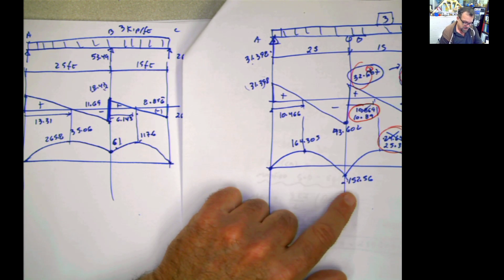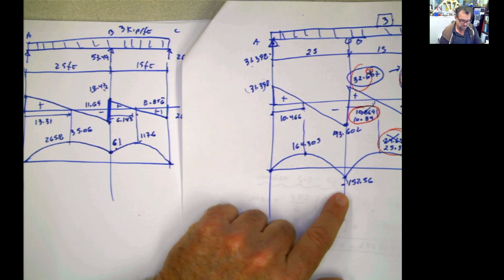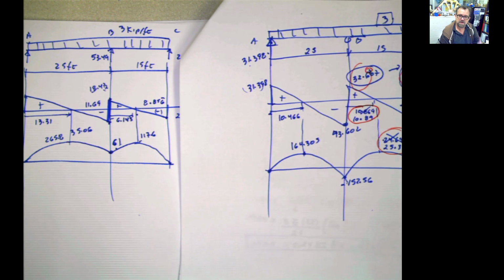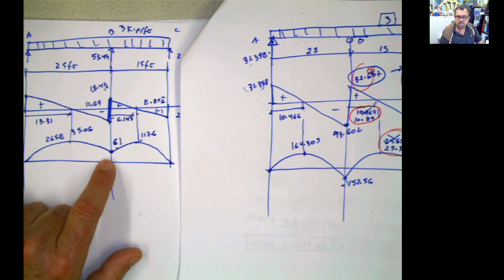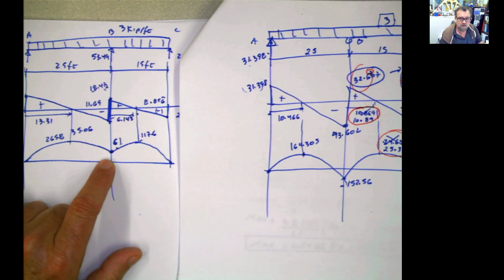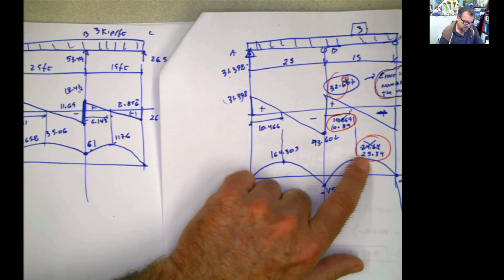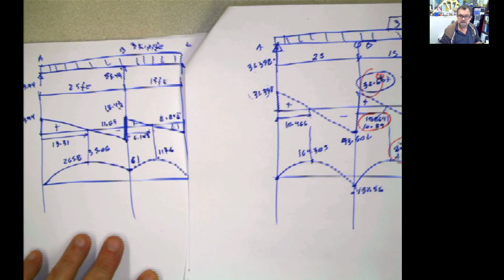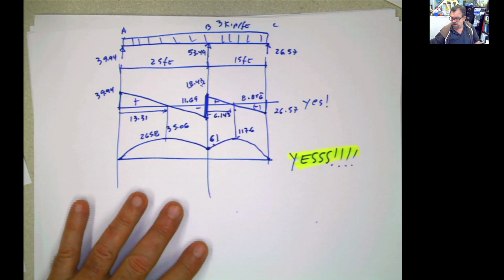Look at what happened with the settlement. Before I had negative 152, and you can say, oh, that is positive. Yes and no, because if I have this, and this is reinforced concrete, for example, that means that I already reinforced the top by this amount. But look what happened now. It's a positive. Did I take that into account before, or didn't I? I don't know. And this value was 25, now it's 117. So that's it. The settlement is a big problem. A lot of people don't pay too much attention to that.